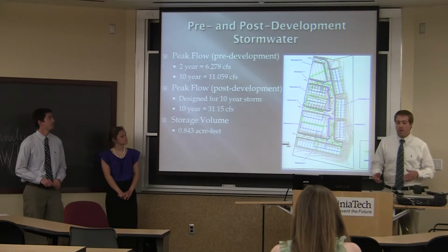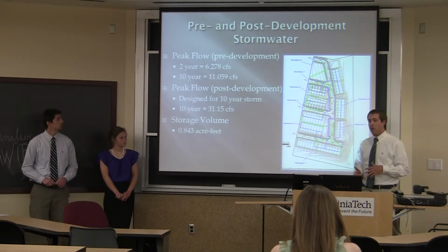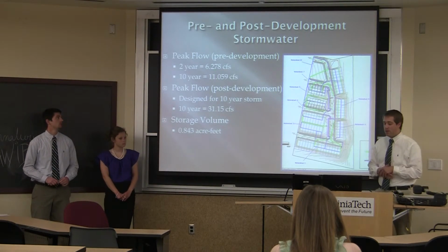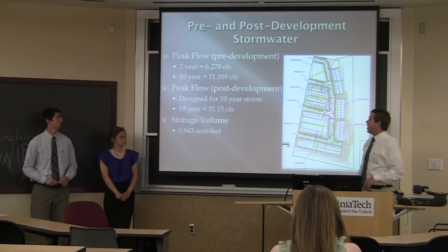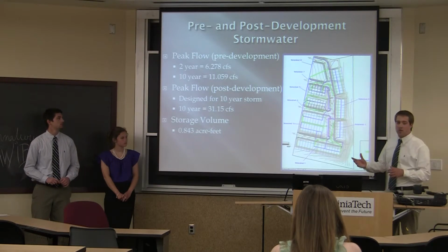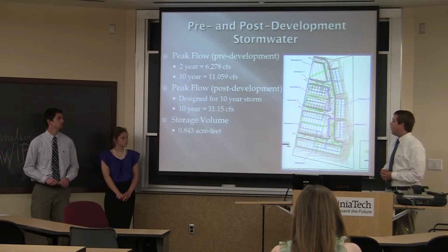All right, so for the stormwater management portion of the project, we calculated the pre and post development peak flow between 2 and 10-year storms. We designed for a 10-year storm, that's why we have the 10-year peak flow right there. It also used the TR-55 method.